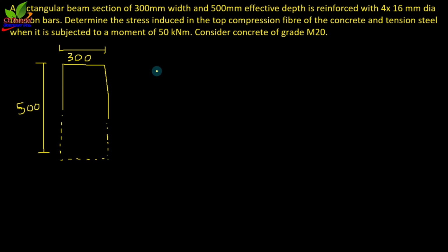Now, reinforced with 16 millimeter dia tension bars, so there are 1, 2, 3, 4, four 16 mm tension reinforcement bars.